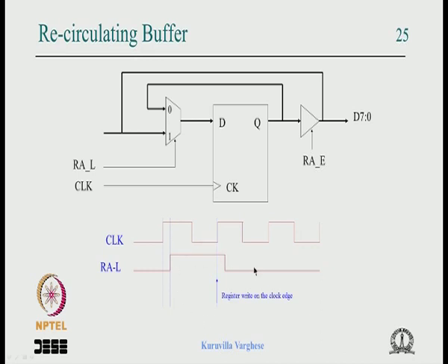very nice, very clean, but power dissipation wise it is really hopeless, absolutely hopeless. It has no relation to when the latch signal is high. All the time it dissipates power. It is just a matter of frequency. Whatever the frequency, it gets switched and the power is dissipated.